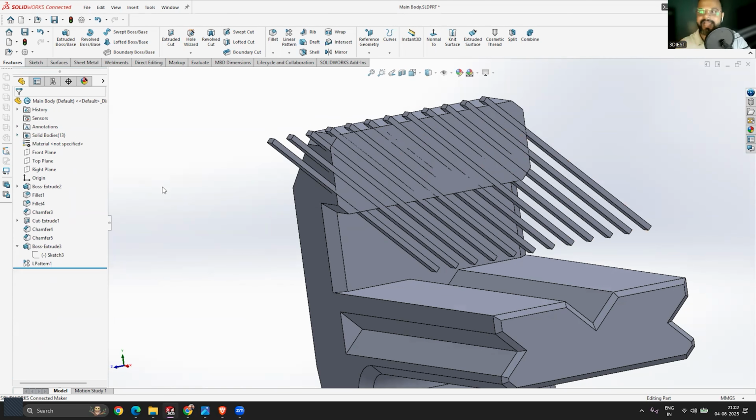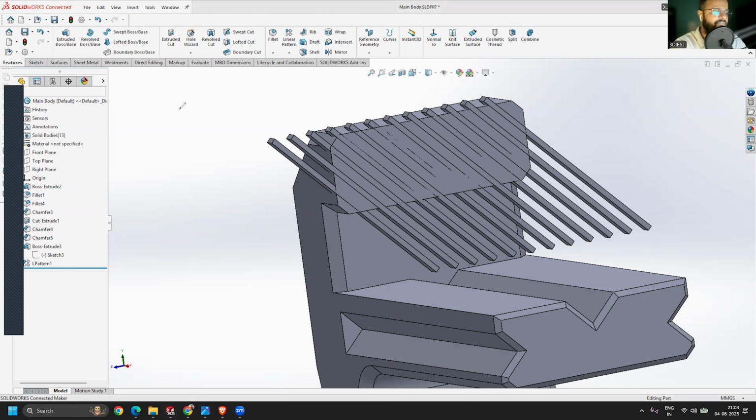Now the next tool that we're going to learn is the Boolean operation tool. And it is very important that you understand the Boolean operation. So first I will give you a small demo. For example, there are 3 Boolean types. Let's say you have a circle and you have another circle. If you make a union between these 2 circles, or combine, you will get an area like this, right? So this is one of the Boolean operations.